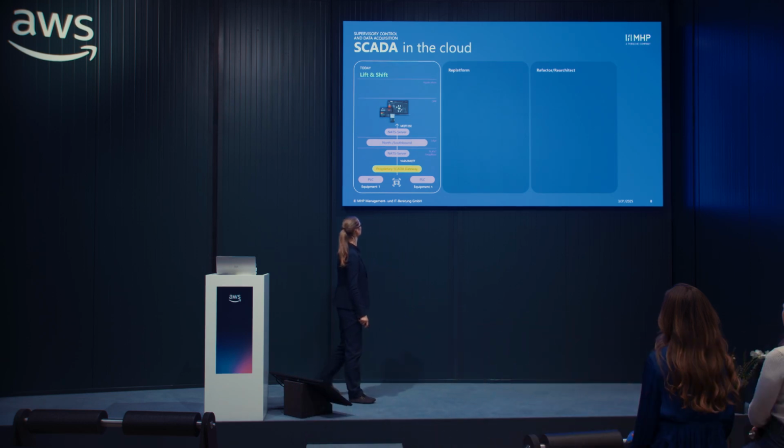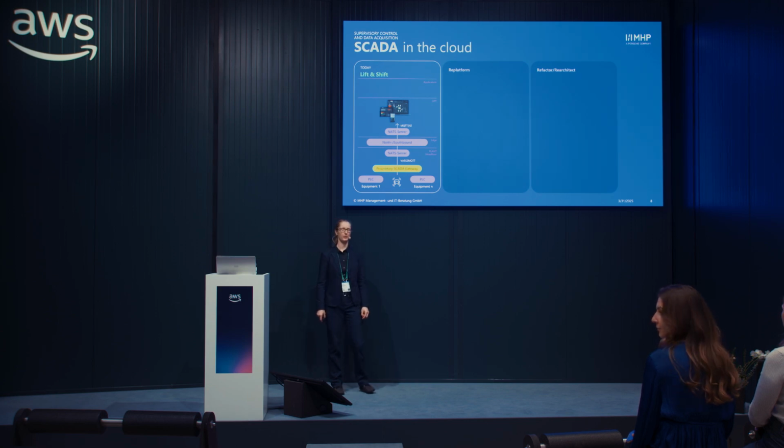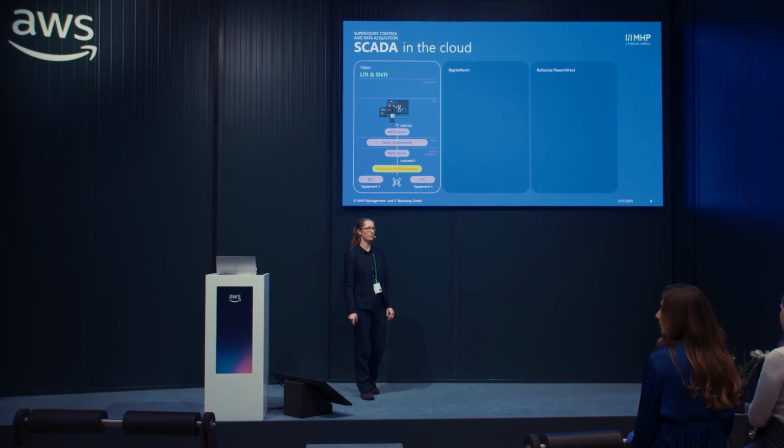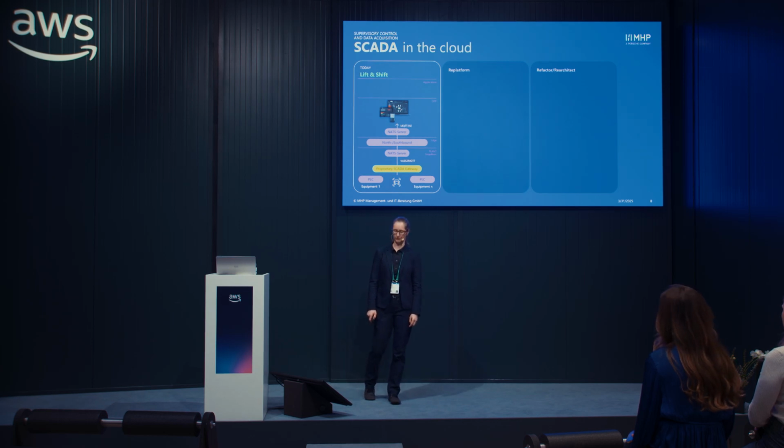What you first have here, the proprietary SCADA gateway on the shop floor, you see here in green. And the SCADA gateway maintains the connection to the PLCs, meaning to the machines on the shop floor. And here we have our first benefit. We are using already established SCADA services. Well, we thought it is a smart idea to use already established services because building up and connecting new PLCs is expensive. And it can be problematic if you have a misconfiguration in the PLC program which is working 24/7 to build cars.